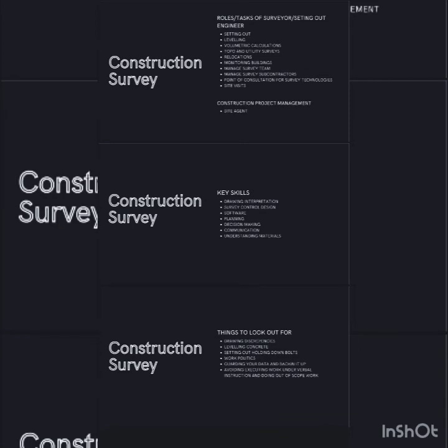All these drawings should have the same detail when it comes to levels. They have to have the same detail in terms of dimensions. That affects your XY. If there is any discrepancy, documents called RFIs, or technical queries, can be raised, saying that this and this doesn't add up. Can you sort us out?